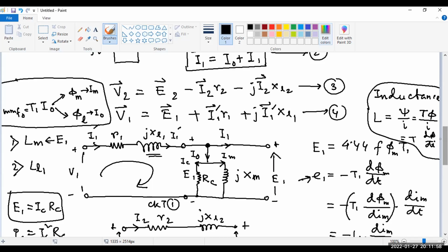Sir, how to find out the reluctance of that path? For a magnetic core we can do it like mean length by mu naught into area of cross section of the core. But for air here, how can we measure the leakage reluctance? How will we decide that?